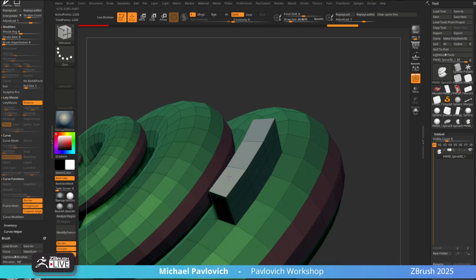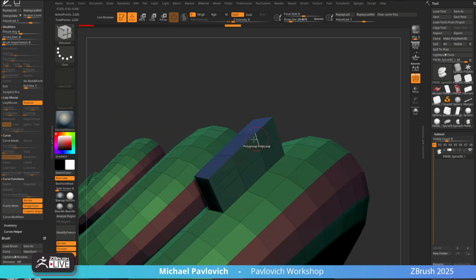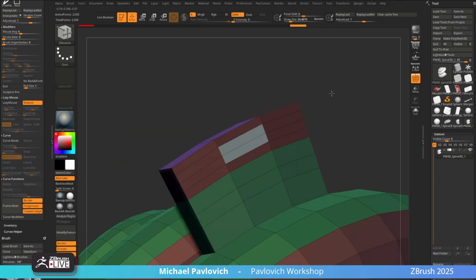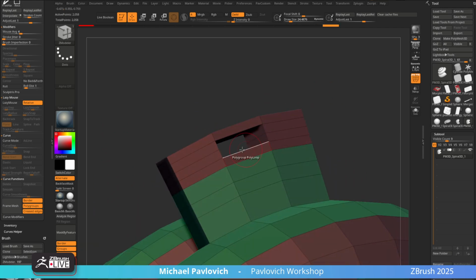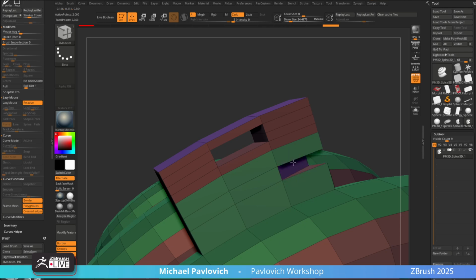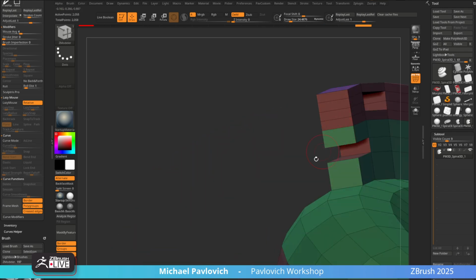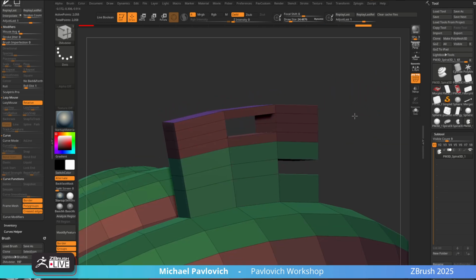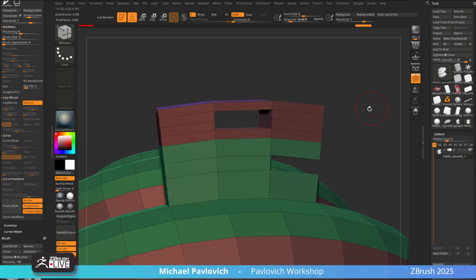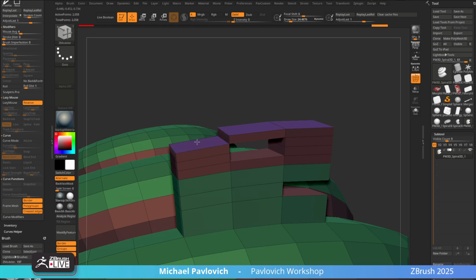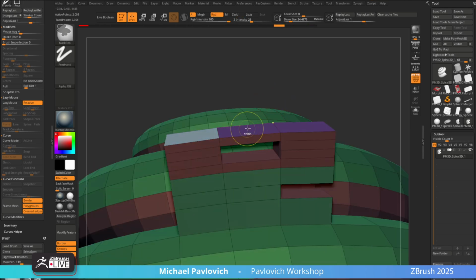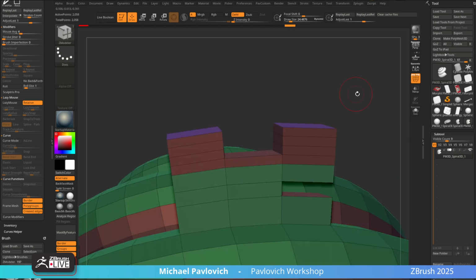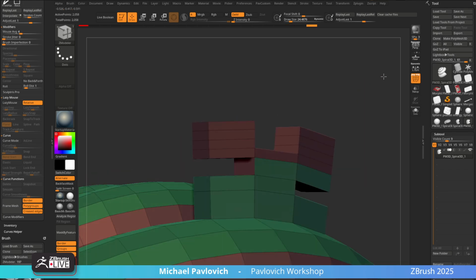I'm trying to, there we go. So QMesh and QMesh and QMesh. And then if you want, you can hold down Alt and paint, and then you can QMesh through, and it'll cut through. It'll auto merge stuff, so you don't have to go through there and delete and bridge or anything like that. It's totally awesome. You can take this one here and just pop it down. Take this one here, pop it down. Oh, it got a little non-tangent over there, but you can just pull right through, right? Alt tap, pull right through. It works great.